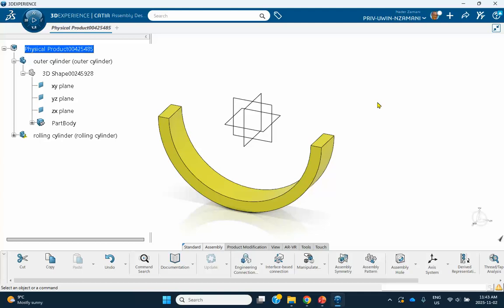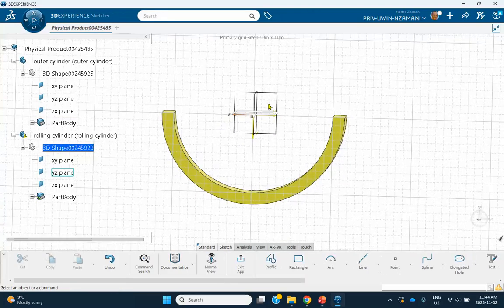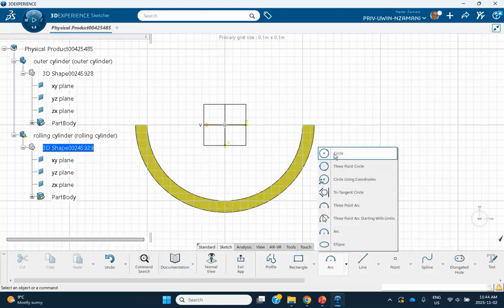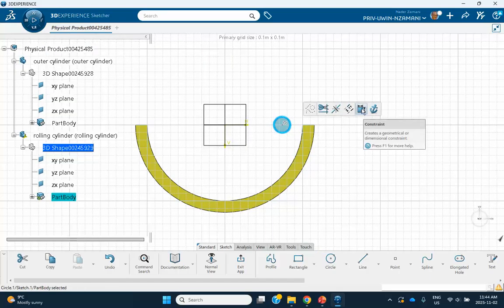Okay, so on purpose, I'm going to draw it on this face. I'll sketch. Let me actually get to the 3D part here. On that face, I will sketch a circle right here at the very top. Let's give it a radius of 0.1. And let me make the distance from this point to that 0.9, so it makes this tangent.